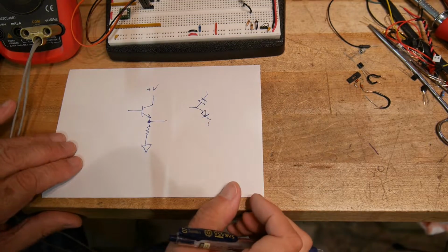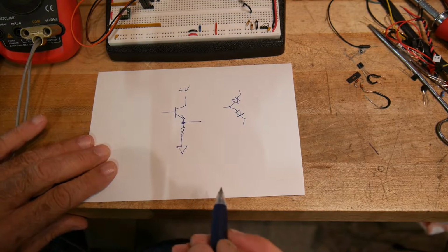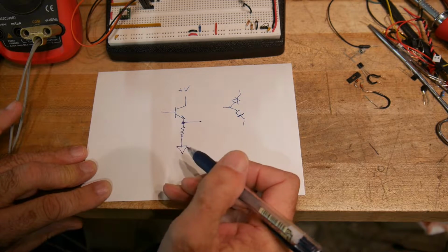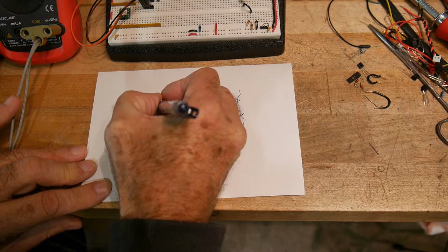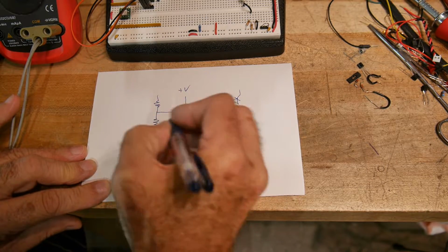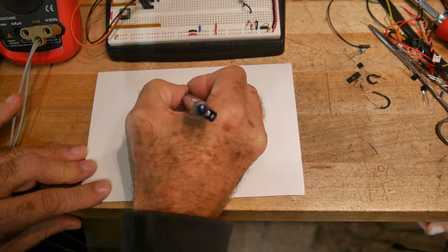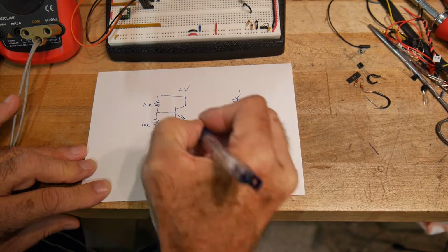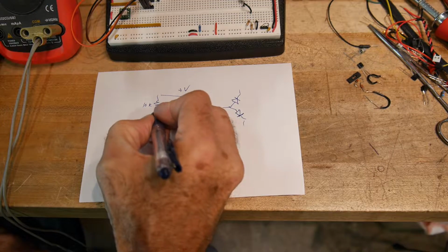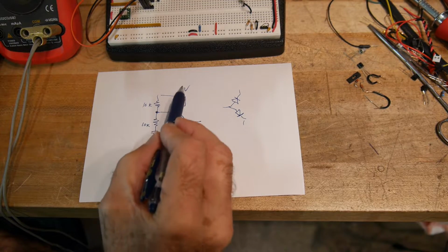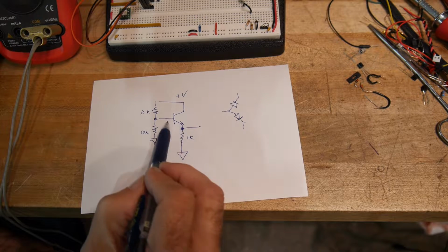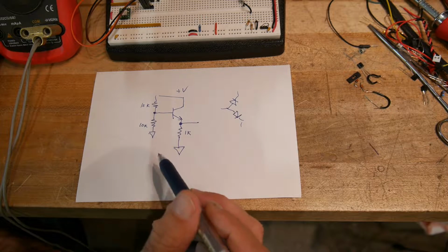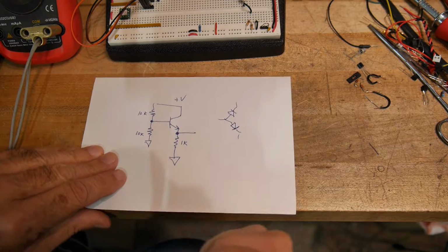And so what we want to do is we want to place a voltage here and then measure the voltage here and look at that voltage drop. So we can do that by maybe putting a couple resistors over here. We'll put a 10K and a 10K and a 1K. Okay, so here we should get some voltage that's halfway between ground and VCC, and then over here we should get a voltage that's a diode drop away from this voltage. So let's do that.